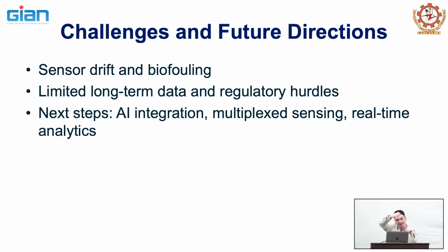You have to stabilize it. It has to be stabilized over a certain period of time. Normally, when you're doing these microneedle arrays, you have a much larger surface area. So when you have the sensor, you leave them to stabilize for 15 minutes till they come down all the way. Any idea, anybody? Why do we have this drift?